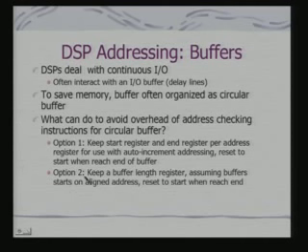And there are two options for implementations. One is you keep start register and end register, and when you are using registers for auto increment addressing, automatically you check whether you have reached the end or not. So, how to deal with the next address? The other option is you have a start address and you keep a buffer length register. So, using this you can manage circular buffers.